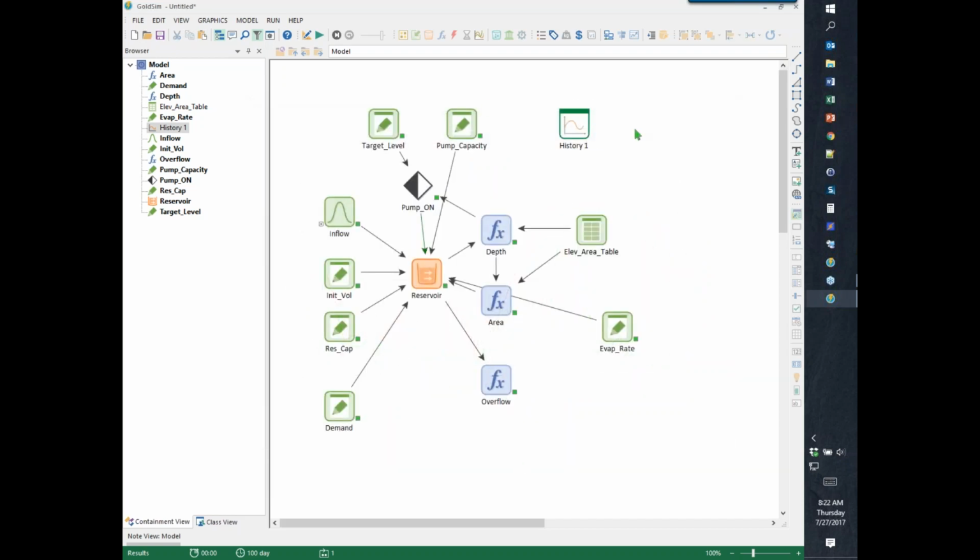Okay, so this is a good, robust way to simulate flows into the pond, or also you might have flows or a pump discharging water from the pond, but using the status element is definitely the way to go. You might also have a lookup table that acts sort of like a rating curve, as your water level rises above a target, you gradually increase your flows using a lookup table. You could do that too.